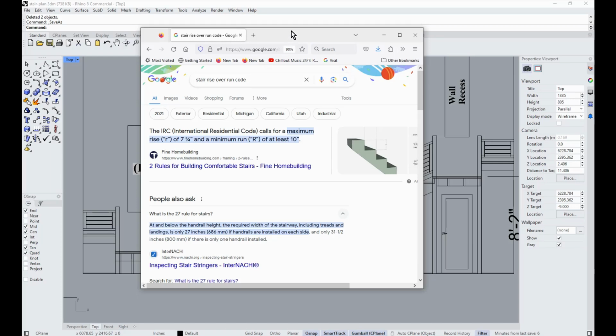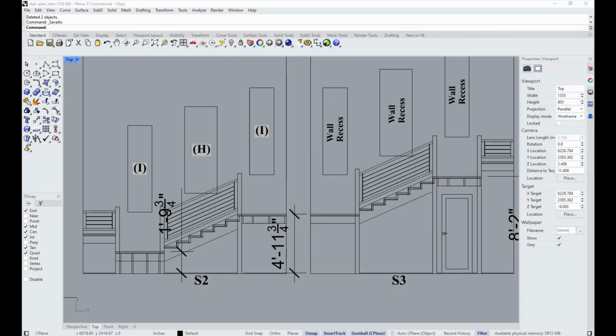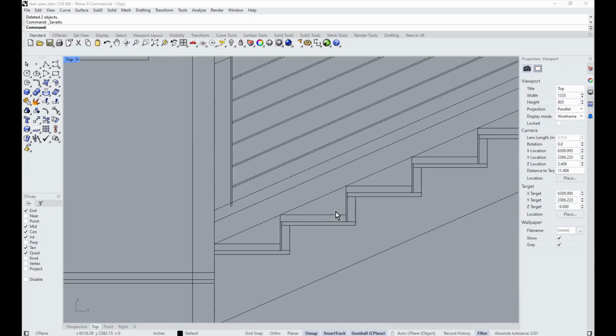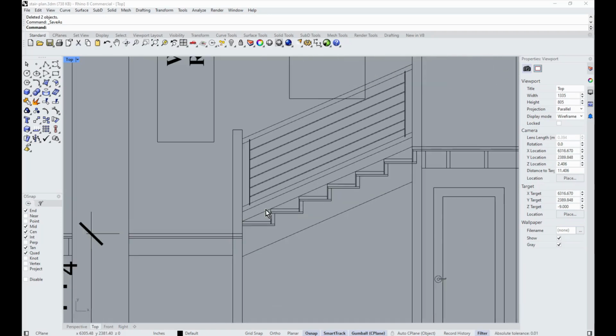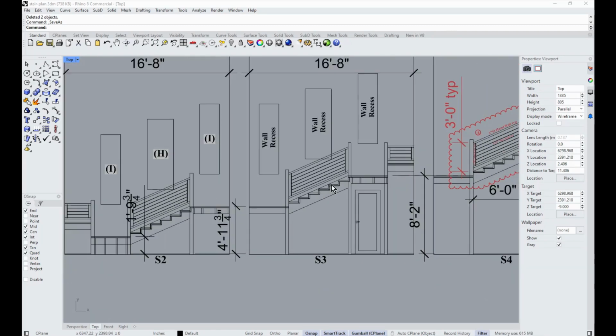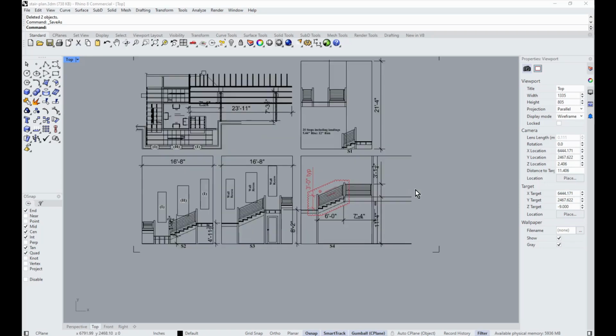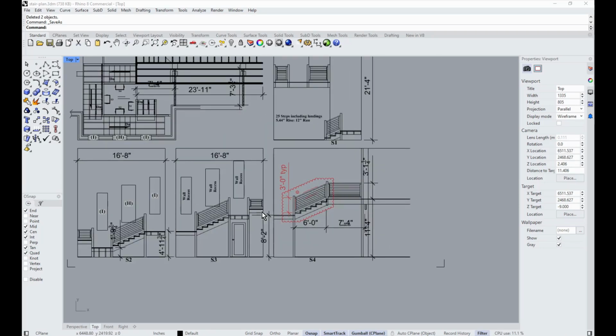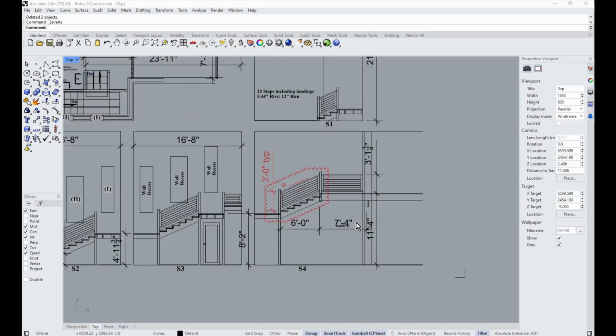The number one compliment I got about this staircase that I designed, and people walk up, is that it's very comfortable to go up. It is roughly 5.5 inches of rise and 12 inches of run. That allows you to use a 2x6 on the riser and rip it if needed. So just showing you the whole staircase, I'll try to recreate some of this so you can see the math and how everything works.